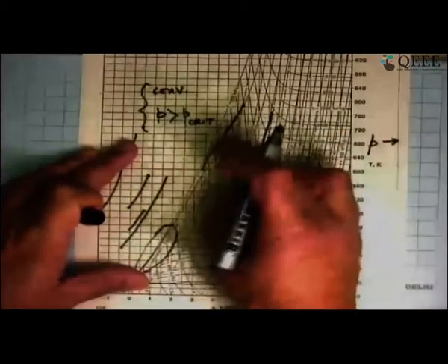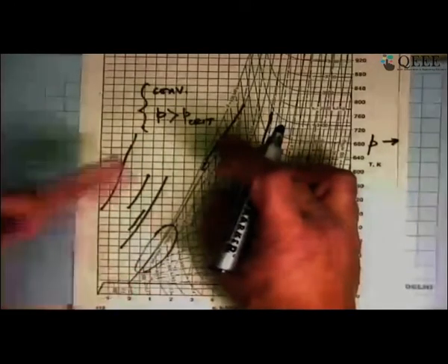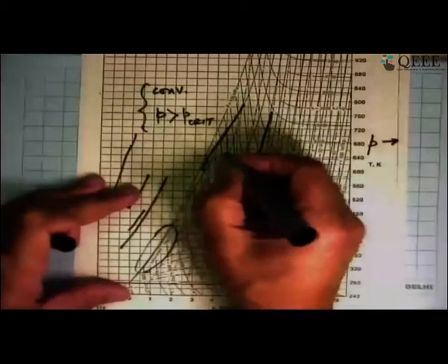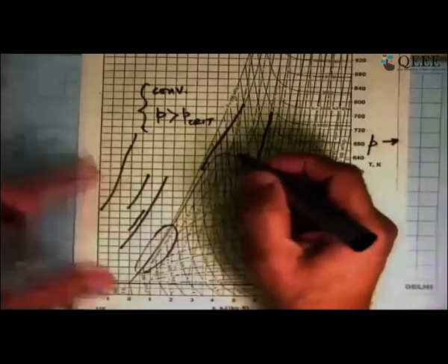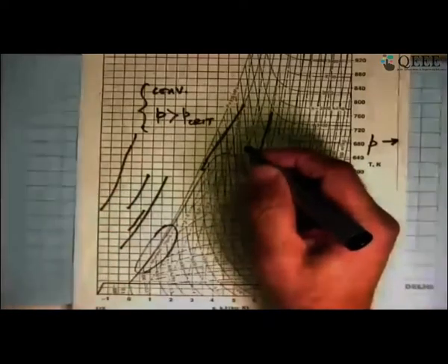Where is this important? In supercritical thermal power plants. Most of the power plants now being put up in the country, the pressure is more than the critical pressure of water, which is 220 bar. And so you do not have any distinct region where you say, now this is where I will do phase change, this is where I will do heating of liquid, this is where I will do heating of the vapor.